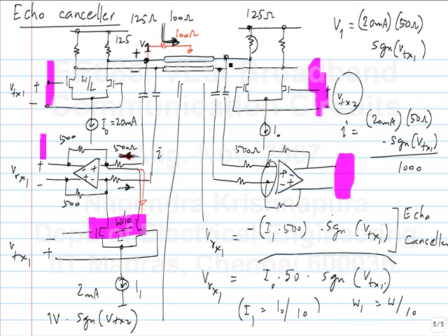And finally, the most serious thing is really the transmission line itself. It won't have an exact 100 ohm impedance. The impedance will have an imaginary part as well. In any case, you will have capacitive loading from the other side, loss in the transmission line and so on. So there is no way you are going to see only 100 ohms here. You will see some real part, you will see some imaginary part. So that is the most serious problem, but the other ones are also problems, mismatch and so on.